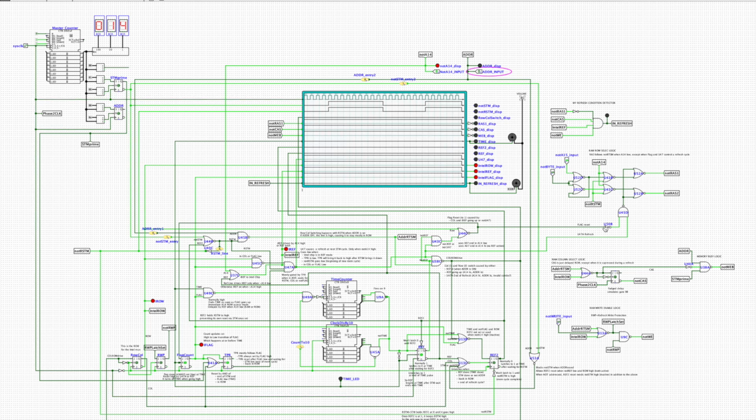And you can see that some of the noodle logic simplified really well and some didn't. The one that simplified really well is the RAS and the CAS. So RAS is very simple. It takes STM, and when it's addressed, it outputs it. So actually, let me change that one here. Let me make it addressed, and we should have RAS. Here is RAS. And then if I address it to, we should get CAS, which is also very simple.